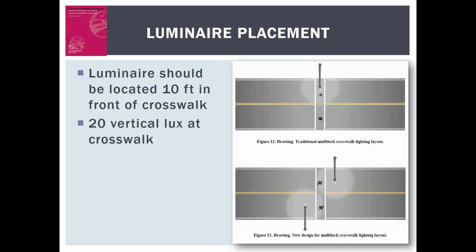And the other issue with rapid flash beacons, if it's push button operated, is that some pedestrians don't push the buttons. As a part of designing for pedestrian safety workshops, we've gone to a location where they had to go from a push button operation for the rectangular rapid flash beacon to an automated detector, because there was such a high incidence of pedestrians not using the push button. But that's not lighting to illuminate the pedestrian. That's just to let the driver know that there is a crosswalk in the area, and the actual visibility of the pedestrian is provided by the adjacent streetlights.